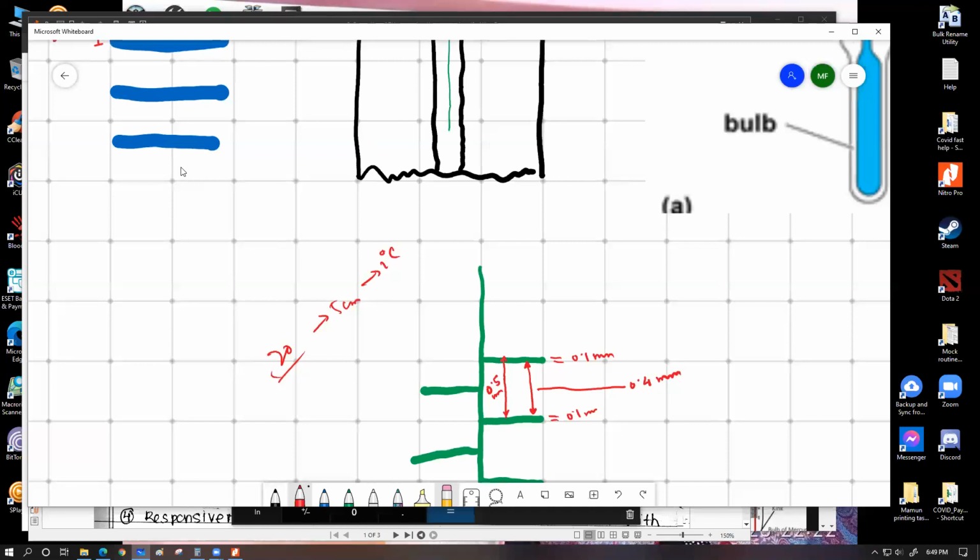So this brings us to the idea that for us to be able to concentrate on close parallel lines and take a reading out of that scale, those lines have to have some convenient gap in between. If you reduce that convenient gap, then the utility or the application for that device becomes limited in terms of the number of people who can use it. So even if we want, no matter how much we want, we cannot divide a certain amount of space into a very large number of divisions. There is a practical limit for how many lines we can actually draw within a certain space.